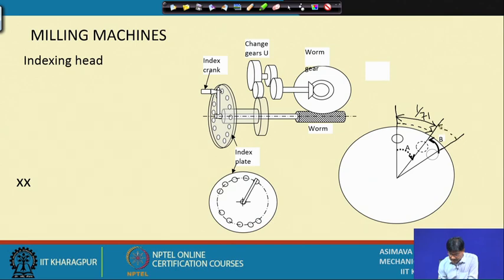That is, you pre-plan the process so that when this crank reaches the virtual position of 1 by 71 second hole, this index plate, sorry, I was making a mistake saying crank, the index plate will rotate backwards and reach this position, so that it will actually place a hole here for the crank to locate itself. So, I can achieve fractional movements of 1 by 71 this way.